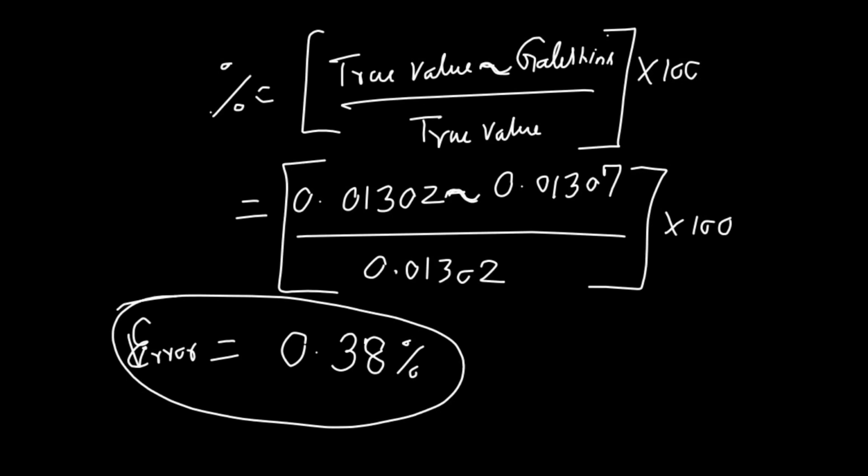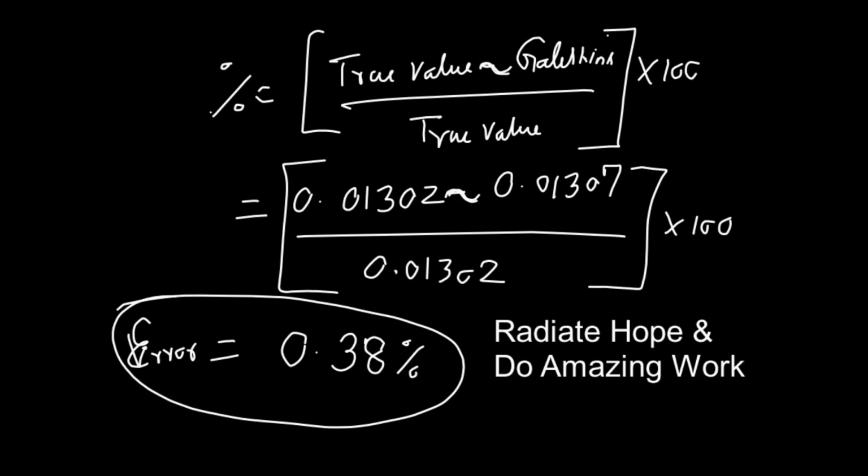Remember, we have already solved this problem by using Galerkin's weighted residual method, by assuming a trigonometric trial solution. So look how powerful this Galerkin's weighted residual method actually is. The error is only 0.38%. It is the piecewise extension of Galerkin's weighted residual method that actually gives birth to the concept of finite element analysis. So please wait. We are going to see what the piecewise extension of Galerkin's weighted residual method is in the next video.